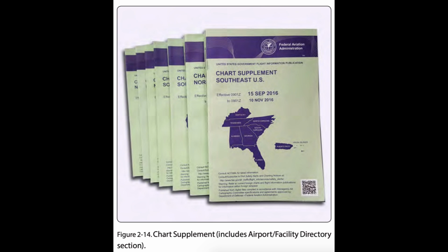Official location identifiers are used in the route description for very high-frequency omnidirectional ranges, VORs, and very high-frequency omnidirectional ranges/tactical air navigation, VORTACs, and intersection names are spelled out. The route is direct where two navaids, an intersection and a navaid, a navaid radial and distance point, or any navigable combination of these route descriptions follow in succession.